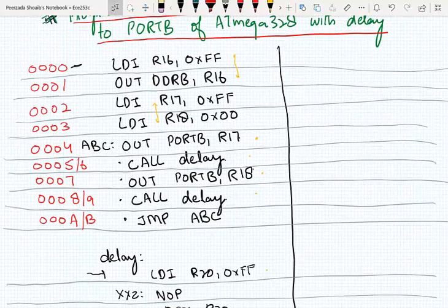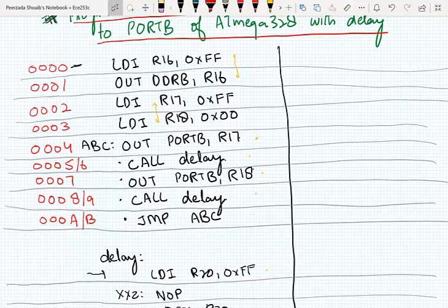So let's get back to a few lectures when we discussed why this instruction is saved. I said the first instruction will be saved at memory location 0000, because when the microcontroller Atmega 328 wakes up, that is, when it's powered on, the first instruction it expects is at memory location 0, because the program counter initially has the value 0.